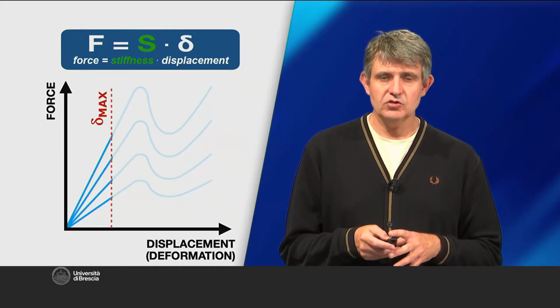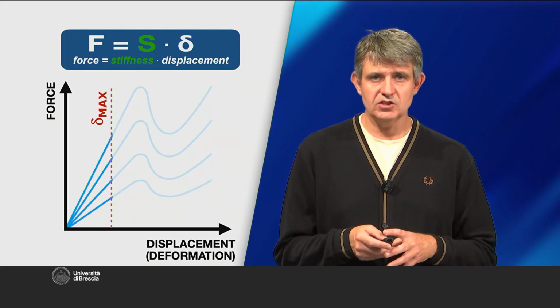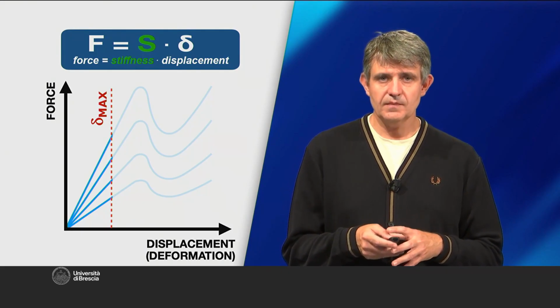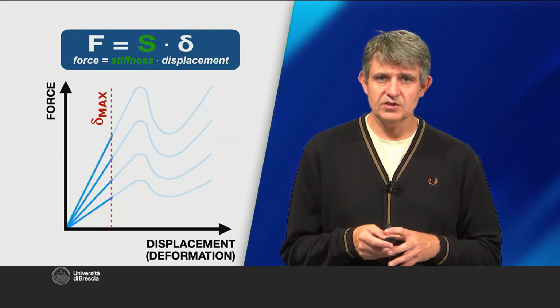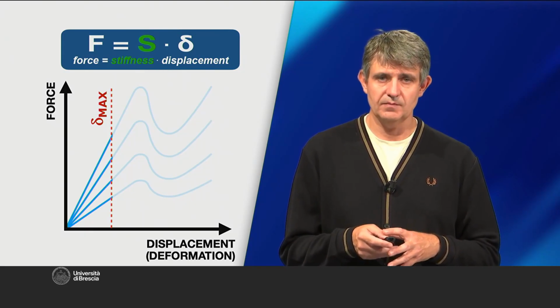The extent of this deformation then depends on the intensity of the force, the type of stress applied, and on the stiffness of the material. The stiffness of a structure relates a cause, the force, to its direct consequence, the change in shape or displacement. In other words, stiffness represents the resistance that a structure offers to a force that tries to deform it.